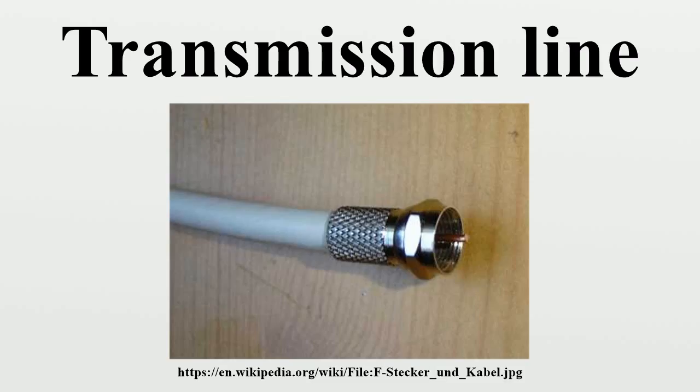Coaxial lines confine virtually all of the electromagnetic wave to the area inside the cable. Coaxial lines can therefore be bent and twisted without negative effects, and they can be strapped to conductive supports without inducing unwanted currents in them. In radio frequency applications up to a few gigahertz, the wave propagates in the transverse electric and magnetic mode only, which means that the electric and magnetic fields are both perpendicular to the direction of propagation.